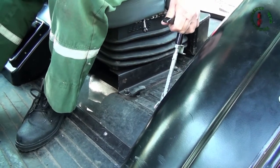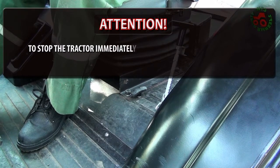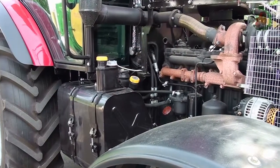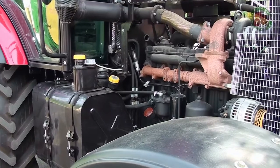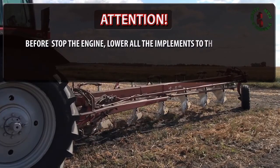Engage the parking brake. Attention! To stop the tractor immediately, sharply depress the clutch and brake pedals. Engine stop. Attention! Before stopping the engine, lower all the implements to the ground.